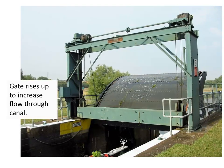That is avoided when you have a curved surface because the hydrostatic forces will just go through the center of rotation. And so now all you have to lift in a case like this is the weight of the gate rather than also having to contend with the hydrostatic forces that might otherwise press it closed.